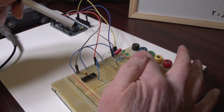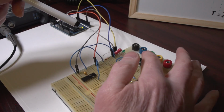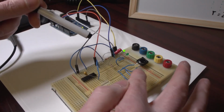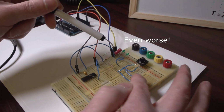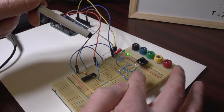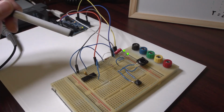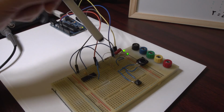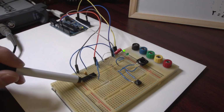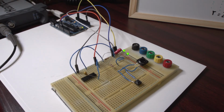So you can see it's not very reliable, it's missed it there. And this button's probably, I don't know, it's even worse. It's not working at all. There you go. So I hope that shows the importance of actually having the RC filter in there. It's about 20 milliseconds, and we're using the Schmitt trigger to make sure that the interrupts work correctly as well, because we need that fast edge for the chip to operate.